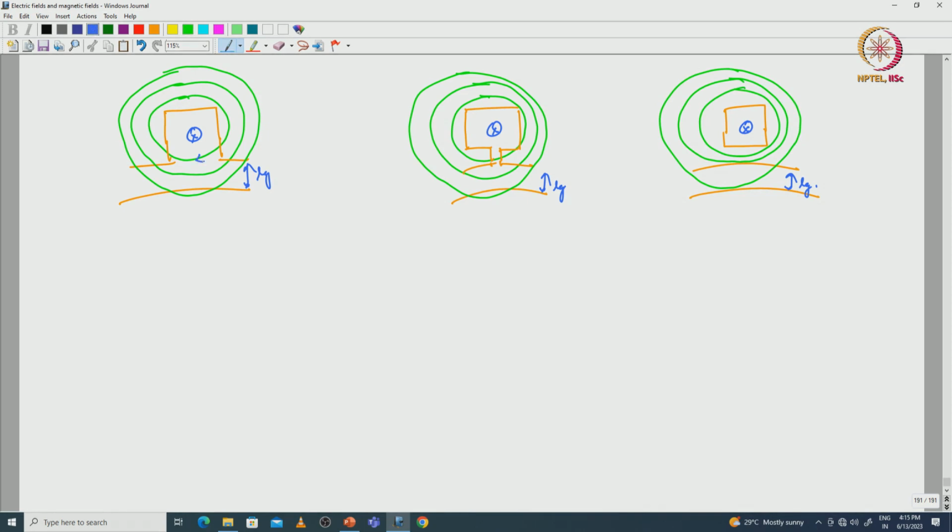For a cross, it will be clockwise direction as per the thumb rule. We can see here the slot leakage flux is less here, and here moderate, slightly higher as compared to the open type of slot, because of the less reluctance value with respect to the closed type of slot in this portion.